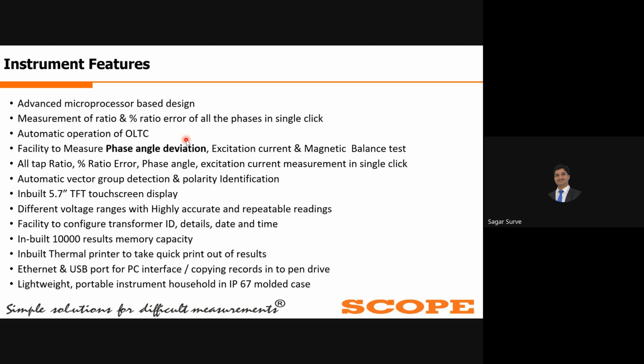It means if you create a transformer ID, then in future, if you are conducting any type of test on the same transformer, all these tests can be saved or stored under this ID only, so that it will be easier for us to compare the results in future. Inbuilt memory can store about 10,000 results.